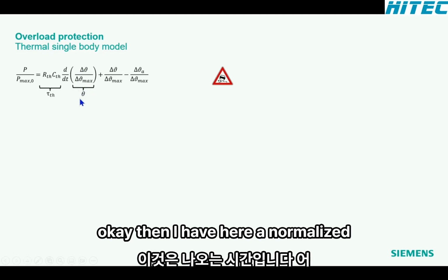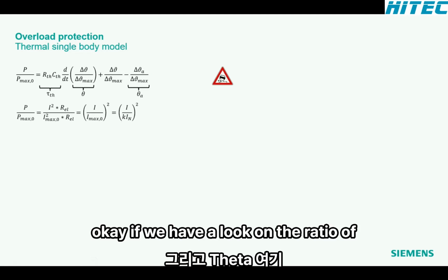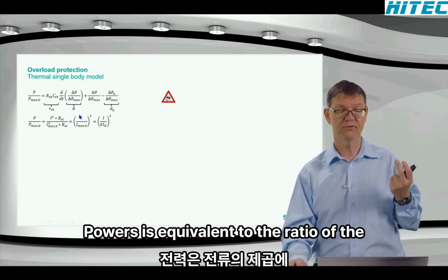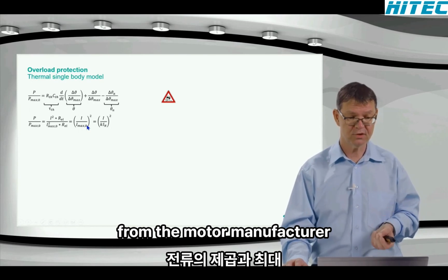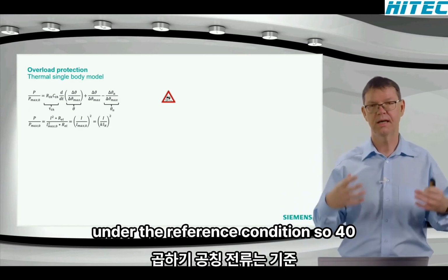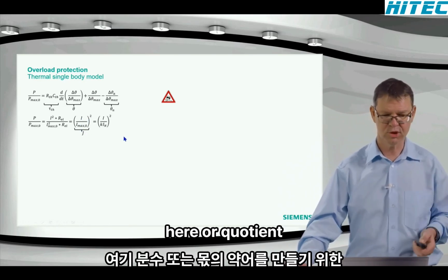Then I have here a normalized temperature, the capital theta here, and the theta A capital for the ambient temperature here. If we have a look at the ratio of the powers, you remember maybe the power is equivalent to the square of the current times the resistance here. So the ratio of these powers is equivalent to the ratio of the square of the currents here. And the maximum current normally I get from the motor manufacturer in the way that it is a factor K times nominal current. So I normally get the K times nominal current is the maximum current which I can put into the motor under the reference condition, so 40 degrees. And additionally, I introduce here a J to make an abbreviation of that fraction here, or quotient.